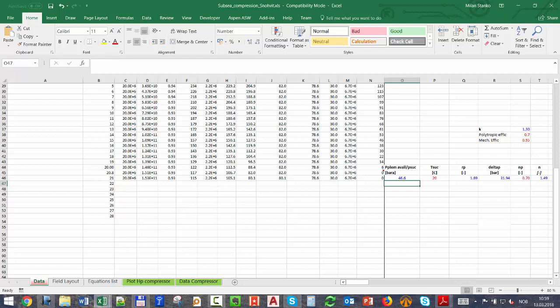And we're using dry gas. It's a bit simplistic, but it shows you all the additional constraints you have to take care of when you're planning for an extension of the plateau based on compression, based on boosting. Okay, power, very important, then temperature, and then to fall inside the operational map.